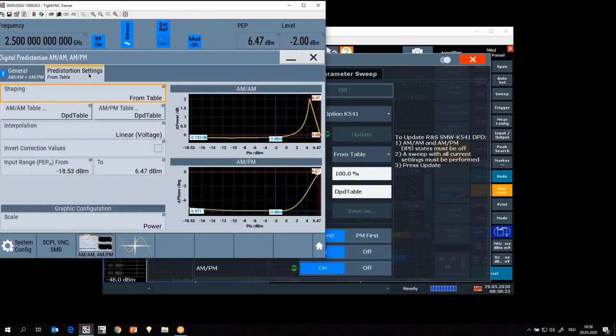And as you might know, you always get these nice little graphs about the DPD curves there. So this is the curve for the lookup table. And basically you can see there's almost no correction here because the device under test behaves linear there. And then our correction goes up to a certain maximum. And then it decreases again. And maybe let's take this one, the decrease, to explain some other behavior. So why is the AMAM correction decreasing from that maximum point?